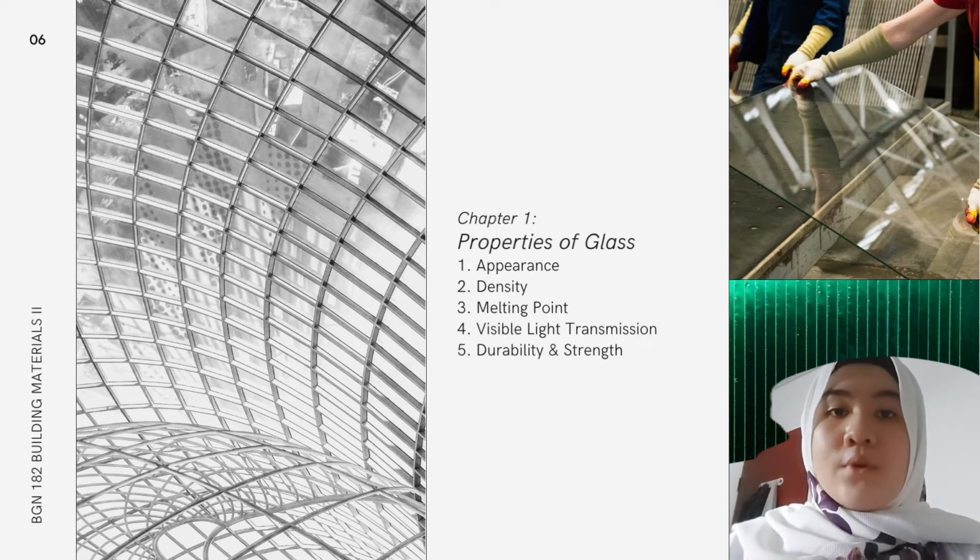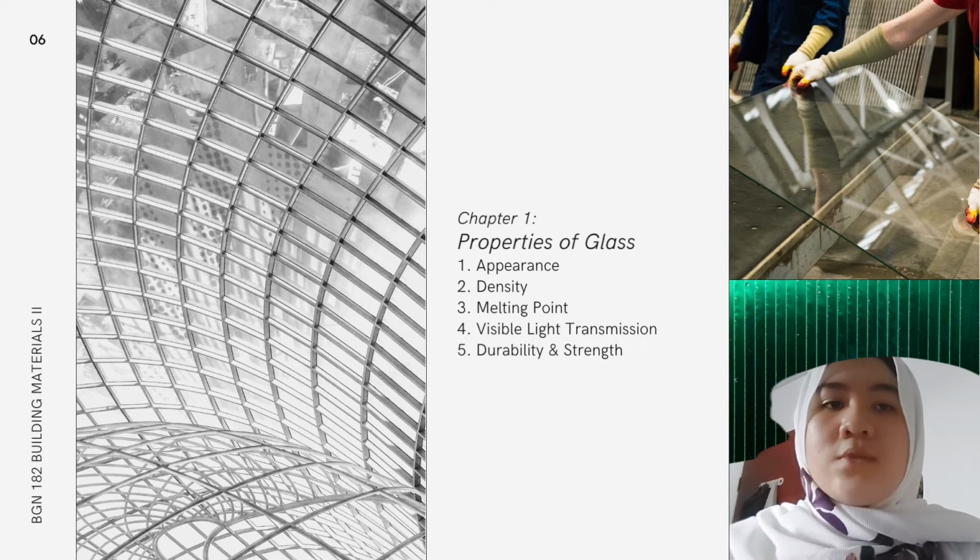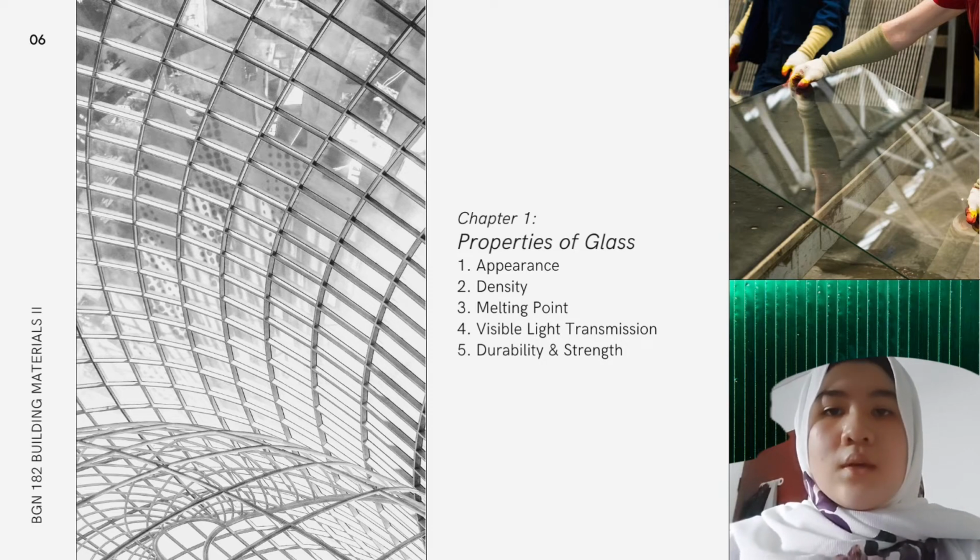Density 2.42 to 2.52 grams. Compressive strength 1000 Newton. Durability: the toughening process creates a strong bond between the glass materials, making it stronger than static glass. Strength properties: tempered glass can be 3 to 7 times stronger than annealed glass, making it suitable for demanding applications with high environmental loads. Available thickness of the glass is 4.38 mm to 20.76 mm.